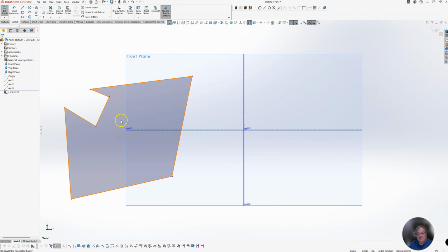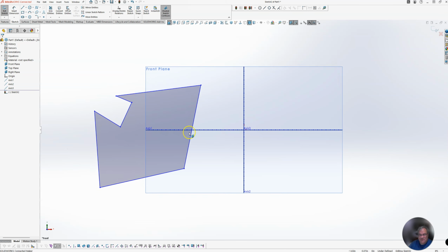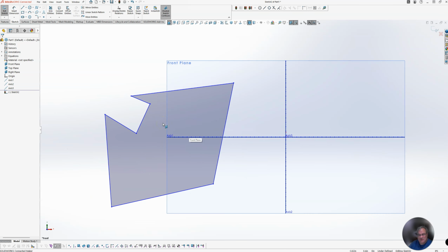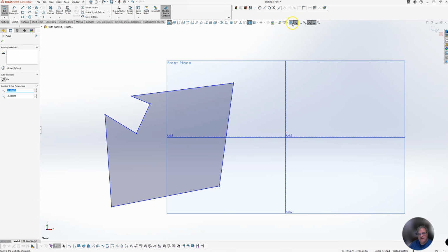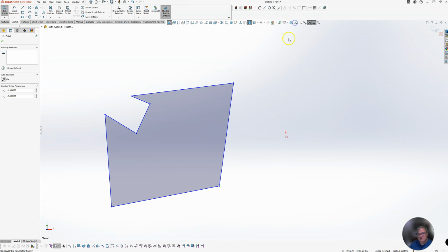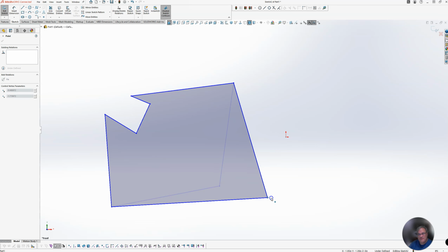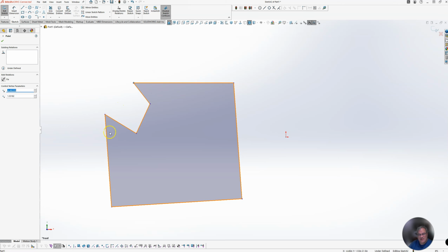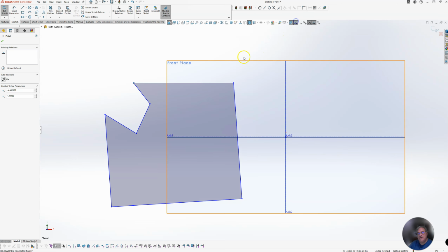So when you have a closed contour, I'd have it shaded. You can turn this on, turn it off. Why you would never have it on, I don't know. And remember blue lines. So I'm going to shut my planes off for a second and my axes. Remember, blue lines mean nothing's constrained. You can move it around. You want to tweak something, kind of get the basic shape and then move it around, go ahead. That's what I would recommend doing.